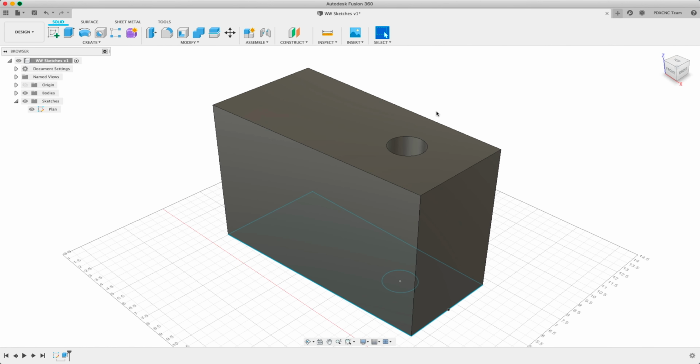Okay, well we don't really like how that looks. It's kind of goofy. So we're going to go back and right click on the sketch down here. As you now see, we have an extrude too. So I can get rid of that by dragging it back, dragging the little current time. So this is like your bar here is where you are in the model timeline.